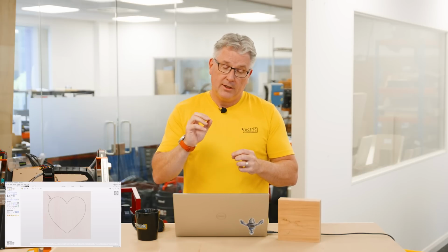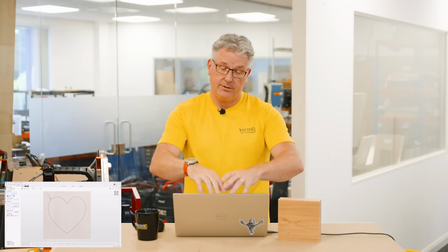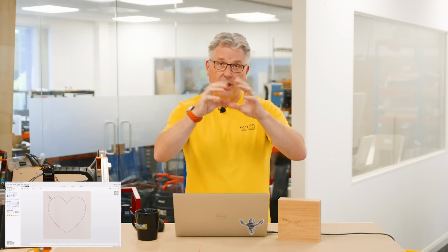about this cross section. If you've never used the Moulding Toolpath before, we have a great video called How to Use the Moulding Toolpath, and you might want to check that out if you'd like more in-depth information about the different steps. I'm only going to touch on the ones that we need to make that little heart. That video is available for you. But what you're going to need to use the Moulding Toolpath is a drive curve, so a curve that you're going to run along a cross section.